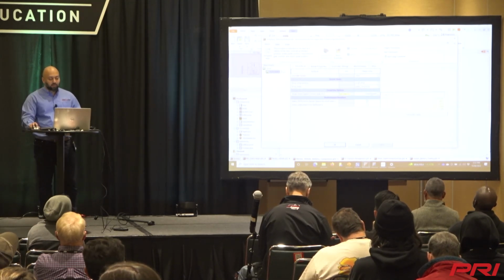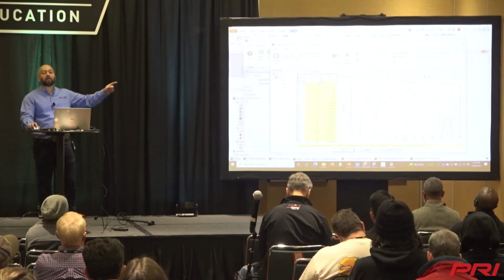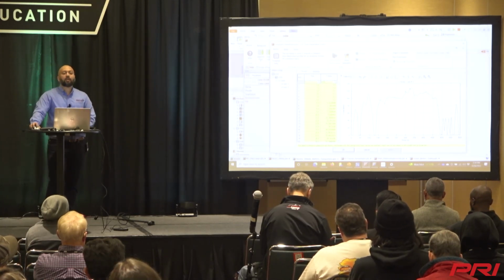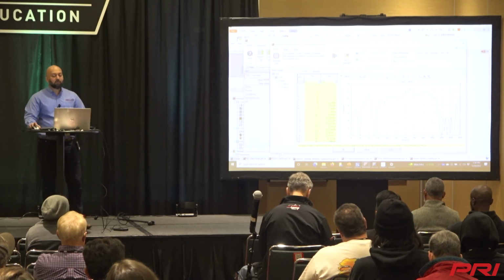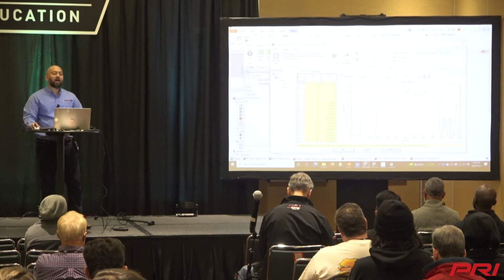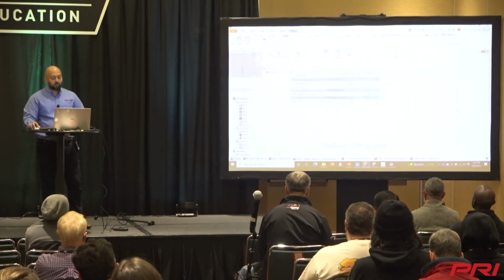In this case, we are going with a US06 for this example. You can see this is the drive cycle it tries to follow. The acceleration event will determine how much power you need based on the vehicle mass and the aerodynamics, and that is then supplied by the power generation of this model.